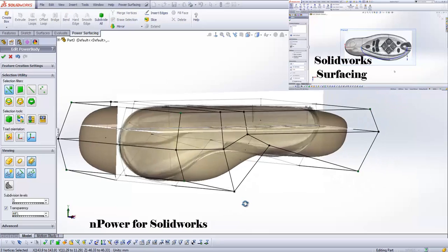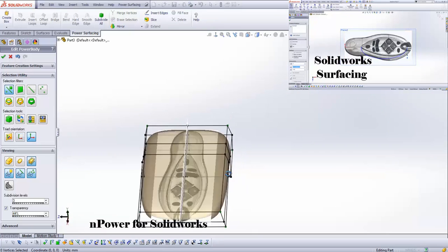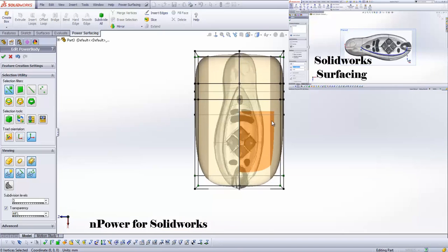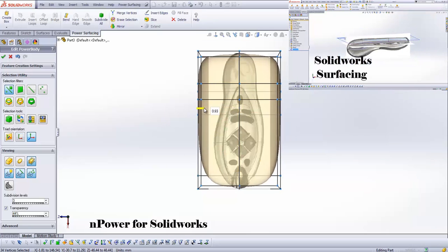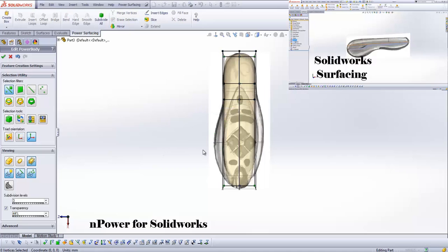So I've got my shape close to where I want in terms of a side view, but I didn't really set up my dimensions all that close for a top view. So I've got this flipped over, and now I'm going to use the scale command. I'm just going to take all of those vertices and scale them in the direction that I'm looking for, the Z direction in this case. So I've scaled that in back, but now I need an extra loop.